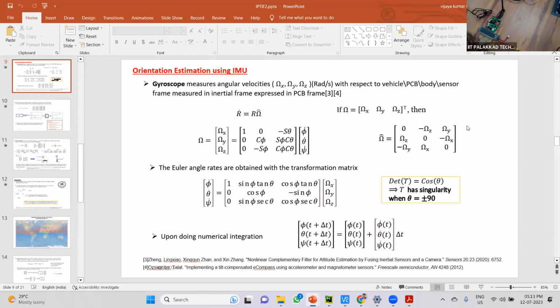So this is another test bed. This is our own PCB developed by some students here. It has a microcontroller. I'm doing the same thing I did with this Raspberry Pi. I'm just taking data from this IMU, you can see the IMU here, to the board, and then I'm sending it to this wireless transmitter and receiver. You can see this wireless transmitter, and this is the receiver that I will connect to my laptop. Okay.